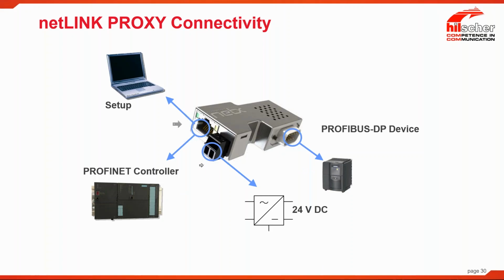And then at that point, you would have a 24-volt power supply that you would need to supply to it. In some cases, if you connect the Profibus connector to a live or a powered connection, it will actually take the power off of that. So depending on what you connect it to, you may not even need that 24-volt connector.